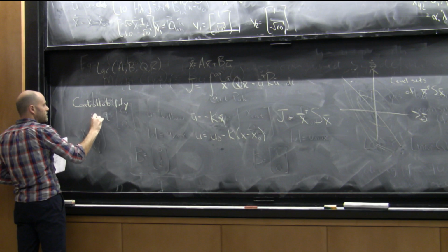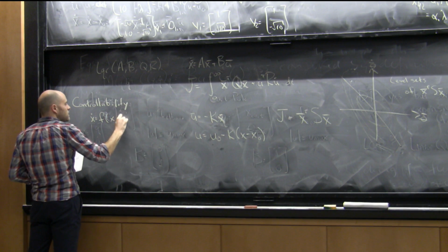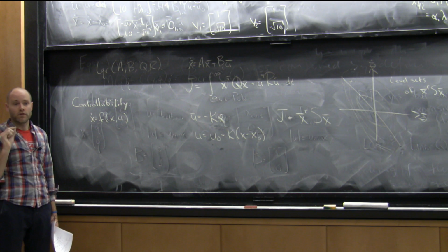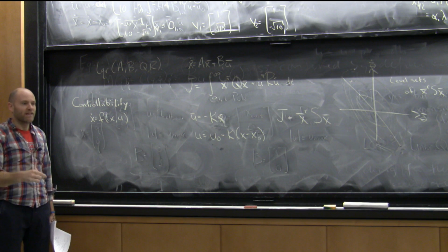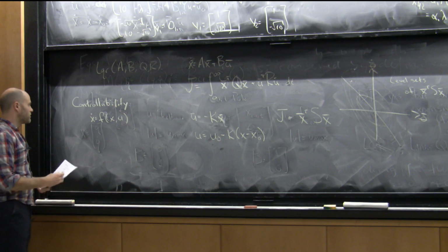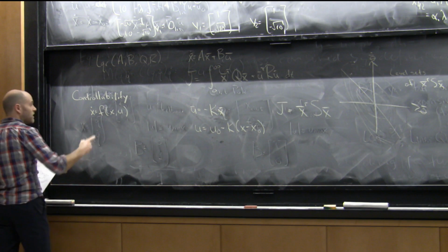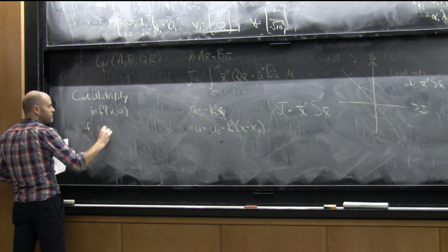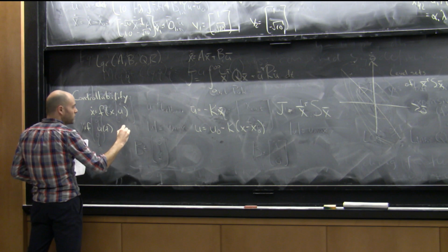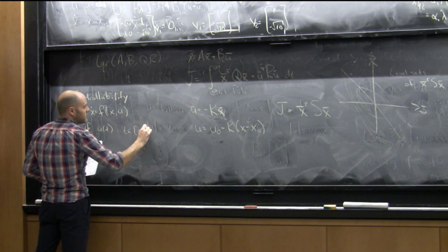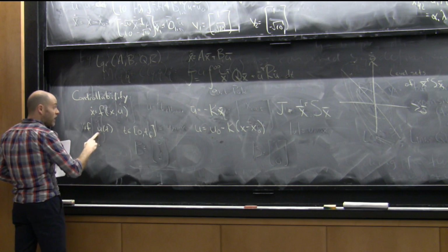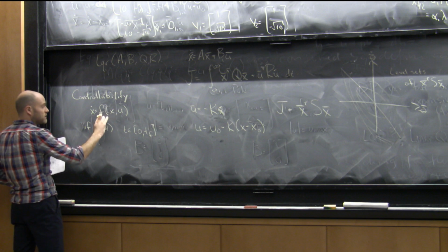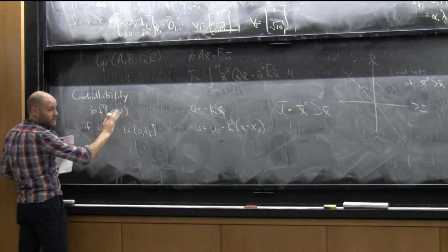So for ẋ = f(x, u), a general nonlinear system, for linear systems people talk about getting to the origin in finite time. But for nonlinear systems, getting to the origin isn't enough to say that you can get to any point. So you actually have to say that a nonlinear system is controllable if there exists an input in the domain, in some finite time. It's an unconstrained u, right? So controllability analysis typically does not take into account saturation effects or anything like that.